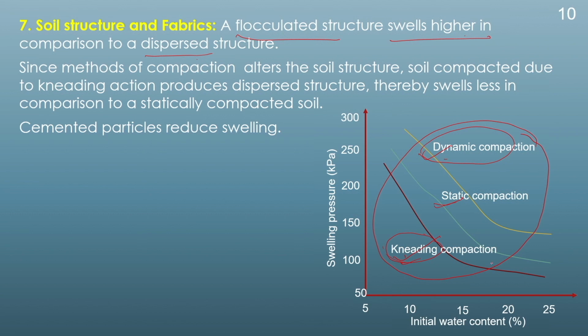In these three diagrams, we can see that for the same density or same initial water content, if the soil is compacted by three different compaction procedures, the swelling of the soil will be different. Similarly, the cementation of the particles also reduces the swelling.